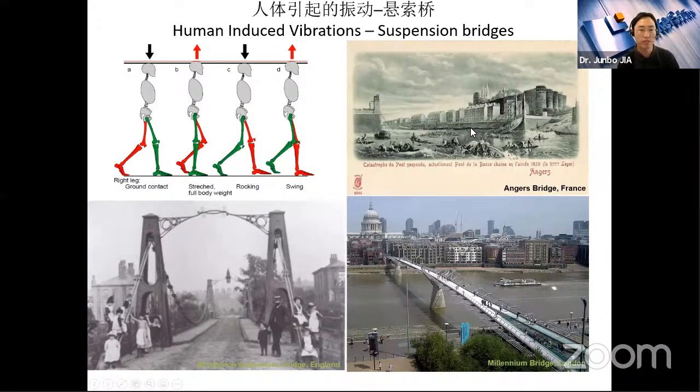But essentially, when the bridge swings horizontally, people also have a horizontal excitation to the bridge. And this horizontal excitation is actually the cause of the resonance of the bridge. Because when you are walking on a very flexible bridge structure, and you try to keep the balance between the bridge and your body, you inevitably excite the structure horizontally. If the structure's horizontal vibration frequency is quite low, for example below 1.5 hertz, you may excite the structure to resonance. This accident caused around 250 soldiers' fatalities, so it's half of the soldiers that got killed.